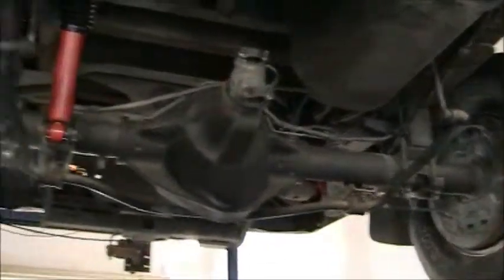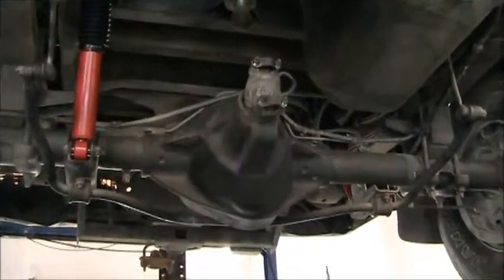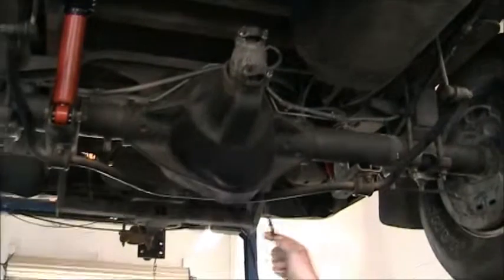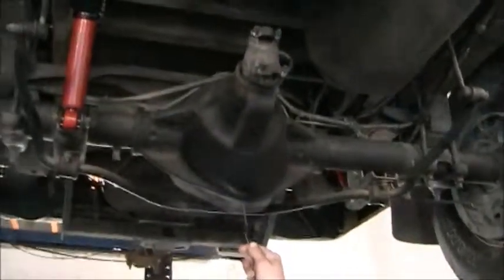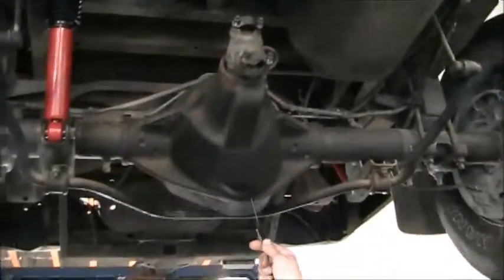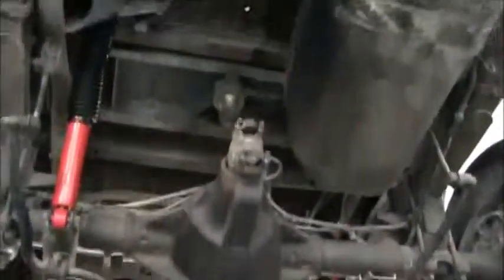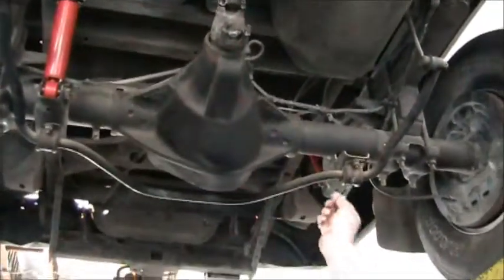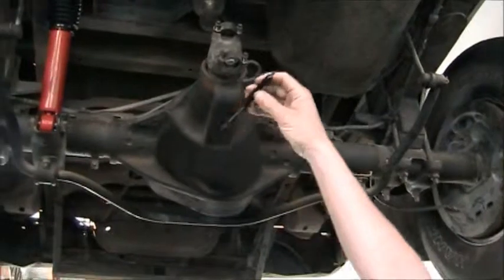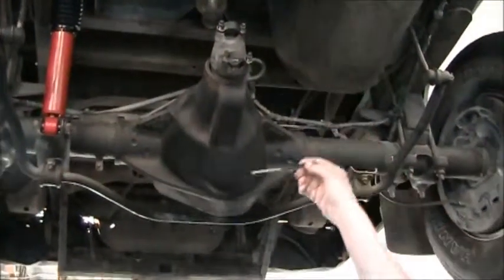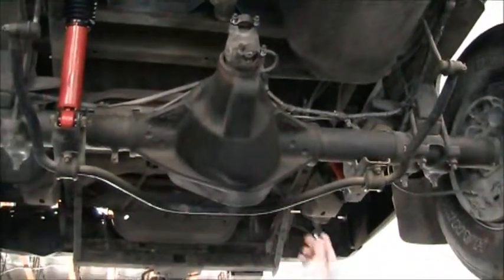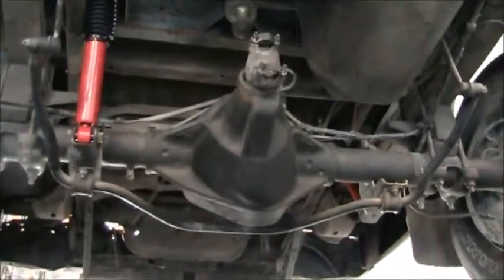Next we'll go to a differential. This is the rear differential. If you notice, it's a solid piece of steel across here. It has ring and pinion gears inside, as well as spider gears and side gears. Those would be called the differential. This transmits the power, and it converts the power from rotating in this direction to rotating in this direction through the series of a ring and pinion gears and spider gears.